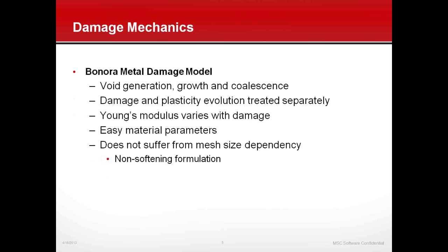The Bonora model is based upon modeling generation, growth, and coalescence of voids, similar to the Gurson model that we already have. It has some special formulations. It's a pretty new model. It's been around for a few years, but we have implemented it for this upcoming release.